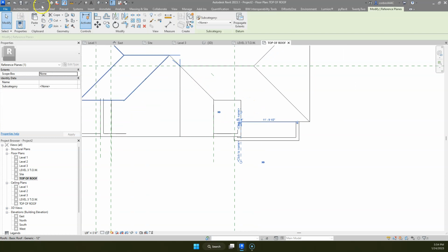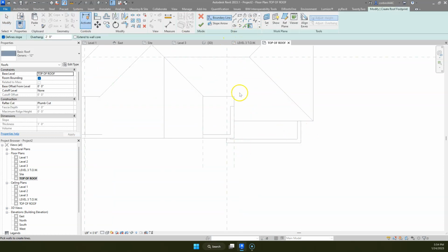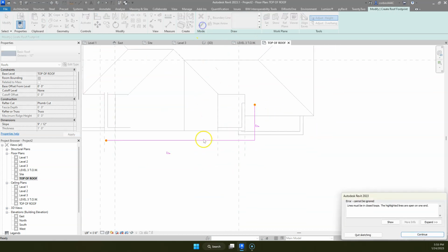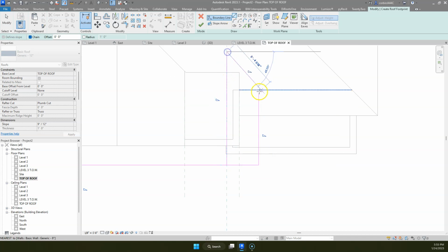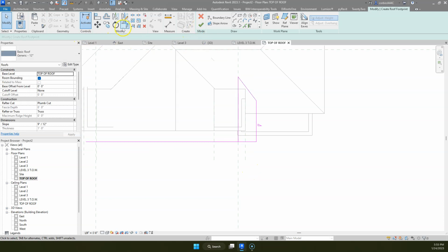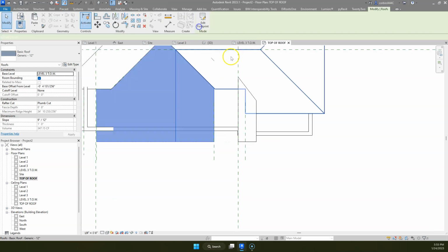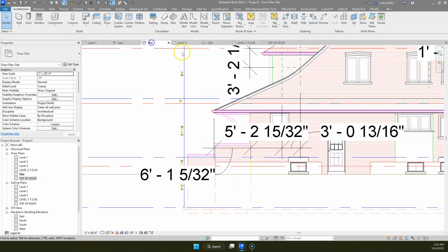So okay, we have a straight section of roof in these parts. So let's go to roof right here. And so we probably have a 2-foot overhang here. And let's just say we have a 2-foot overhang there. And the roof goes to this line. And it's something like that. Turn all of these off. And then I'm going to bring this out so it's in line with this. So this slope is much less. So let's figure out the slope of that.